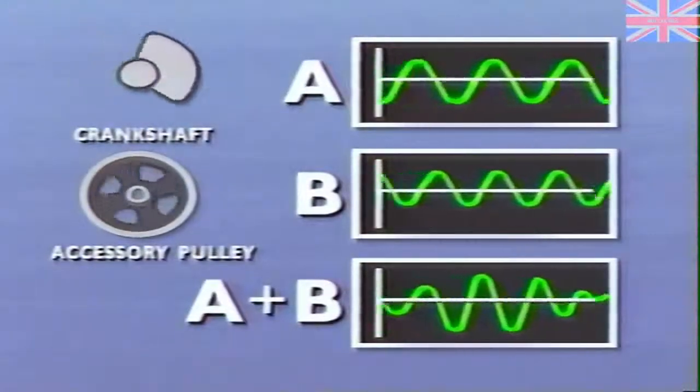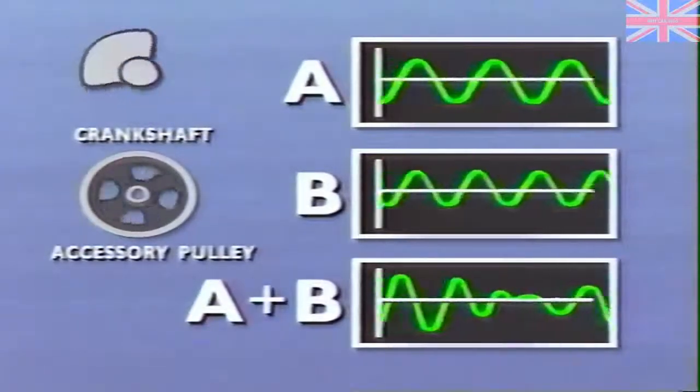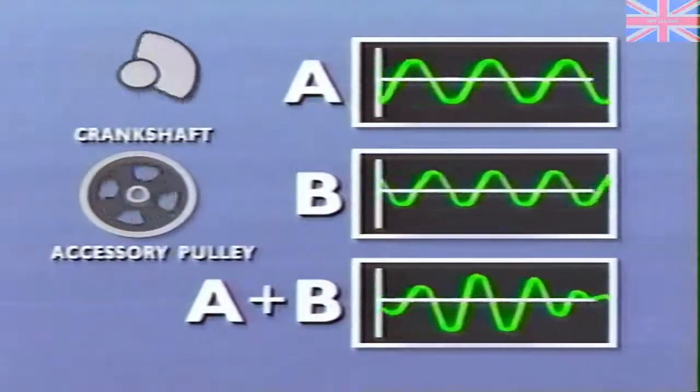Beat is one of the most difficult noises to troubleshoot because it involves combinations of two or more different component frequencies causing a modulating sound like this.